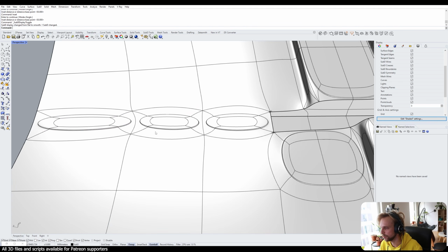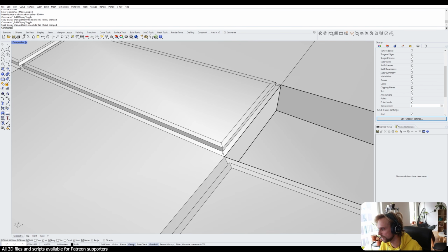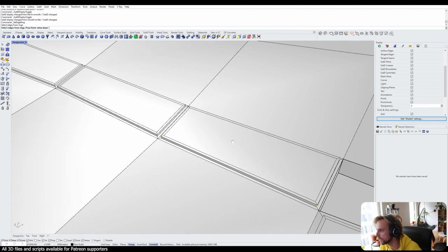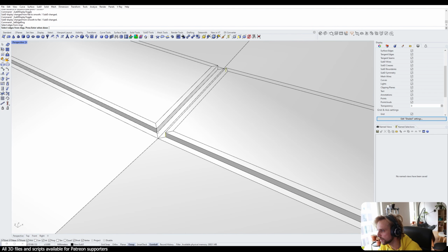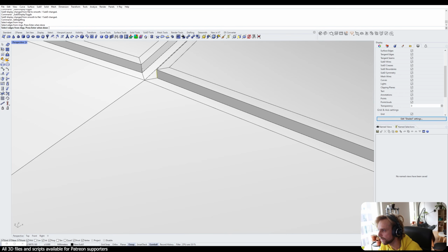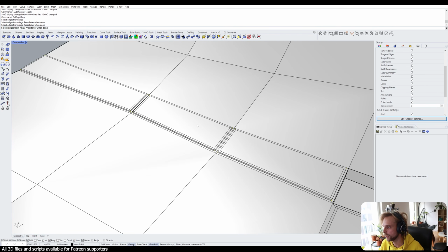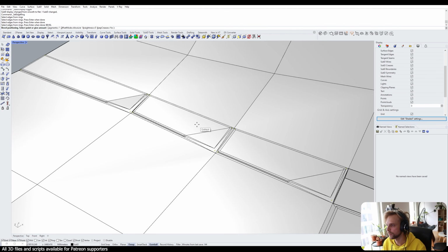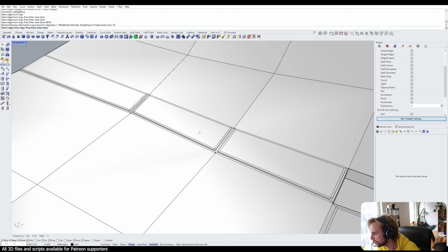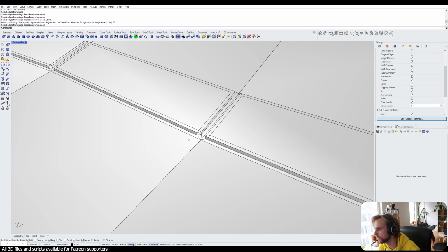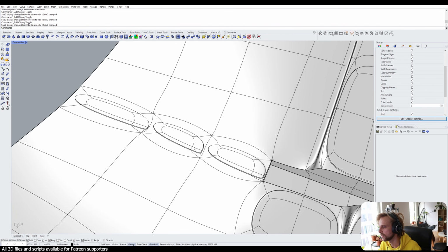So I get these three little slabs here that I can go to subd tools and choose this edge ring tool to easily select all of the vertical edges here. And then use bevel on them with the same, I think I keep using 50, right? 50. Wait, I think I messed up.